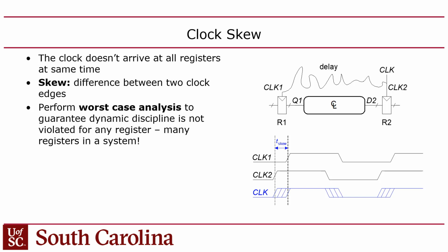Right? Likewise, for contamination delay, if the source flip-flops are running early, if the clock edges that are triggering the inputs look like they're running early compared to the destination, meaning the clock period is kind of being stretched out, then you may violate the hold constraint because you're giving the inputs a head start. They're getting a head start because their clock edge is earlier than expected, relative to the destination clock edge. So you have to consider the skew time as well.